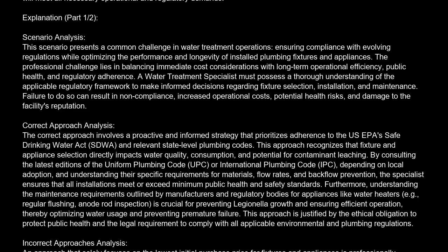This approach recognizes that fixture and appliance selection directly impacts water quality, consumption, and potential for contaminant leaching. By consulting the latest editions of the Uniform Plumbing Code, UPC, or International Plumbing Code, IPC, depending on local adoption, and understanding their specific requirements for materials, flow rates, and backflow prevention, the specialist ensures that all installations meet or exceed minimum public health and safety standards.